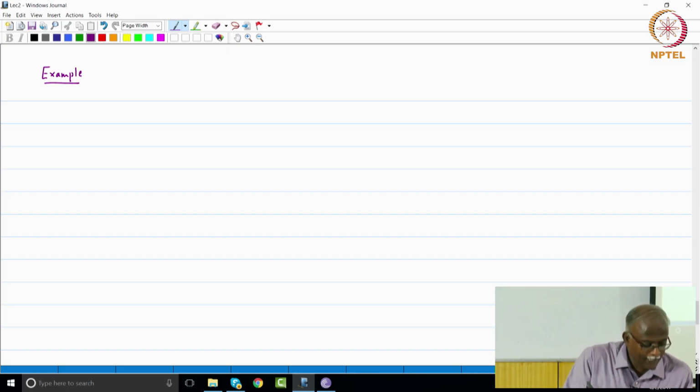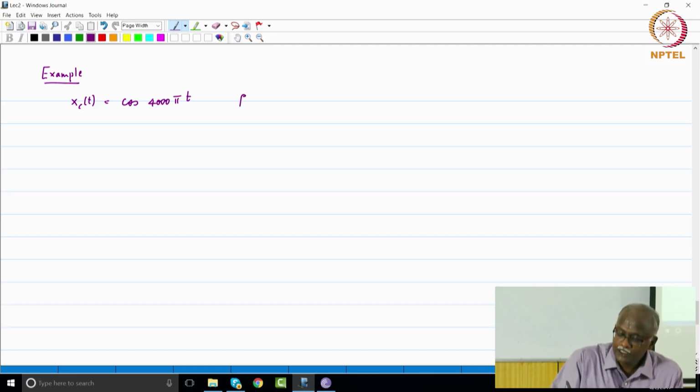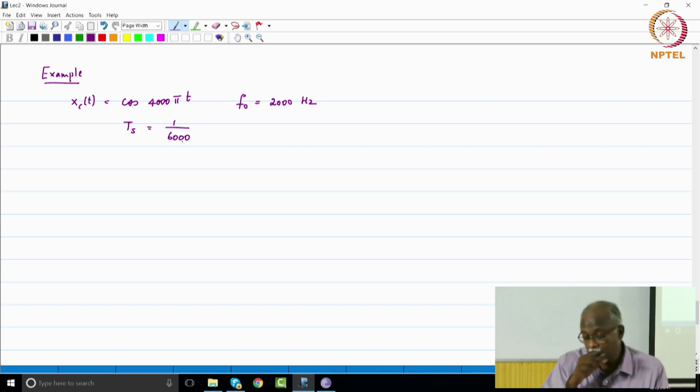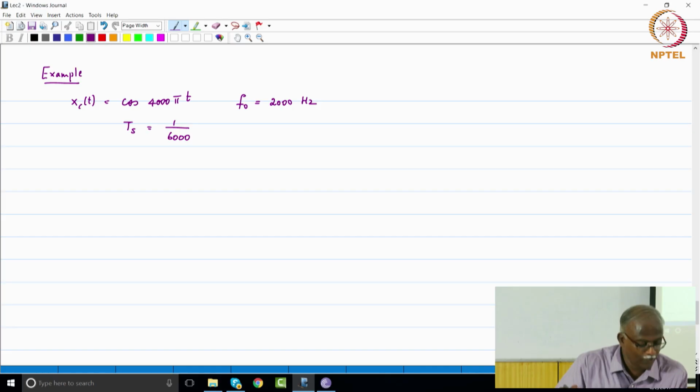Now, if I had a continuous time signal, cosine 4000 pi t, that is my signal. This means the frequency is 2000 hertz. If I assume a sampling period of 6000 hertz, or a sampling frequency of 6000 hertz, or a sampling period of 1 by 6000, what is the discrete time signal that we receive?